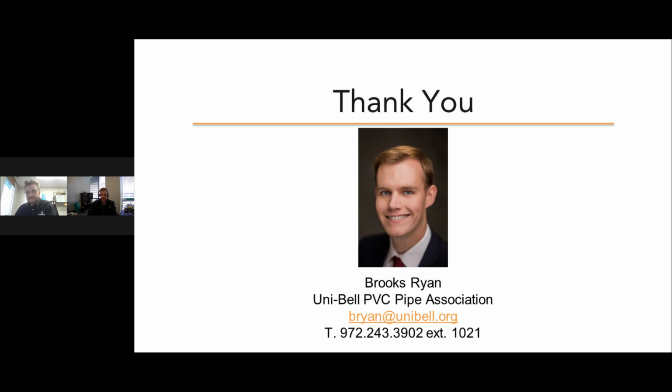Yeah, there's a handful of testing that we have going on currently. Presently, one of them is a series of cyclic testing done for PVCO. Historically, there's been a number of cyclic tests done for PVC pipe. That's what's been slowly used over time to develop the cyclic life calculations used for PVC pressure pipe. But for PVCO, there's not been a whole lot of comprehensive testing done, enough to formulate an equation or set of values for a cyclic lifespan of PVCO.